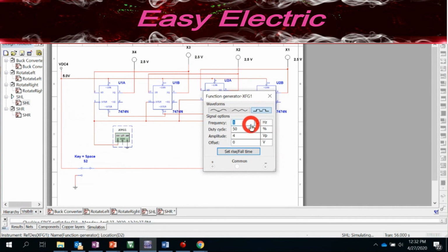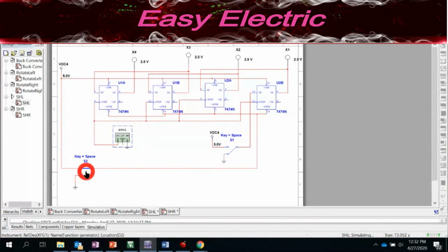You change the frequency. If you have a smaller frequency, it means you have a bigger period, so the shifting to the left will be slower. So I changed that to 0.2, from 0.5. So definitely it should be slower. Again, I initialize the circuit, give 1, then turn that back. See, this time it is slower. Shift to the left, shift to the left, it should be gone. That's gone. If you again put 1, then put 0, it moves here, then should be here, then here, then will be gone.